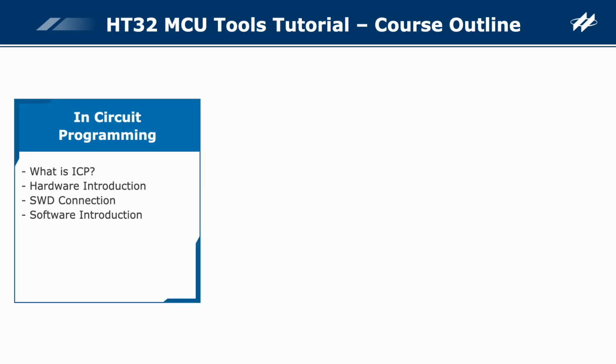In-circuit programming. ICP stands for in-circuit programming, which means that the chip has already been soldered to the target board and allows firmware updates without the need to unmount the chip from the circuit. It usually works with the debug interface and does not require any pre-programmed firmware. This course will introduce the ICP connection, hardware, SWD connection, and software used during the ICP operation.